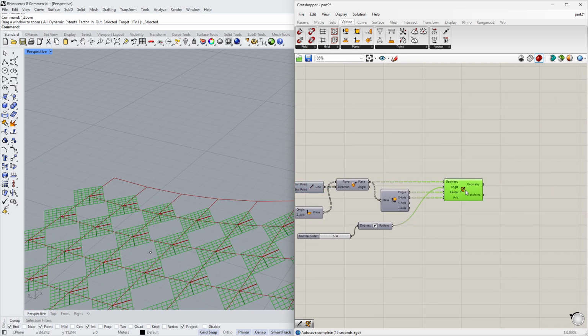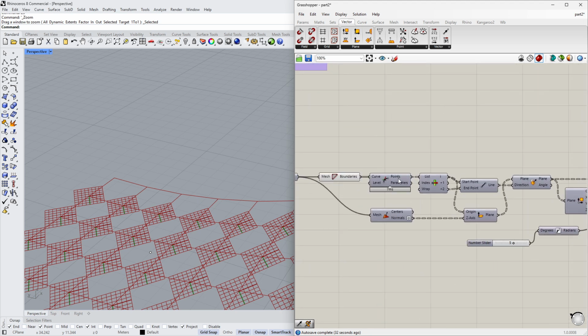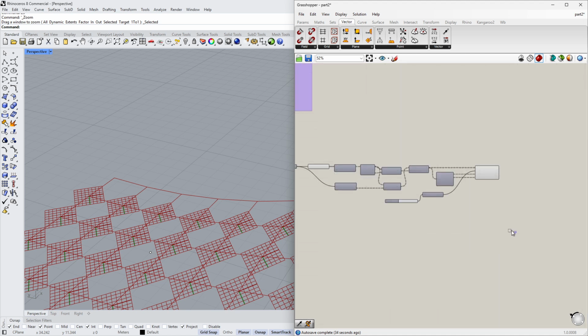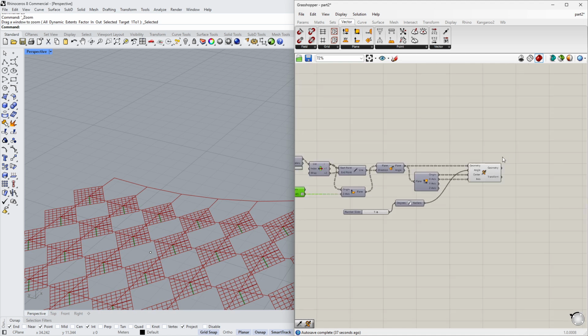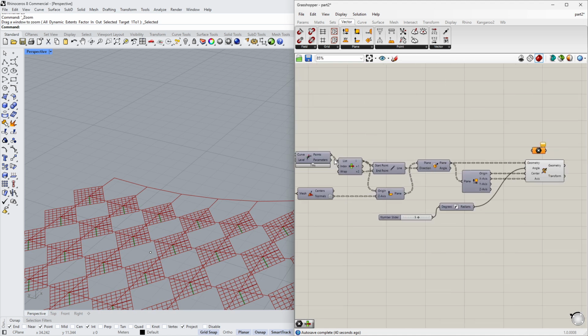So now we have our plane. The next thing we need to do is to project that double curved face on top of the plane so we get a straight flat panel. So for that, again, we need to get the points. Let me move this one a little bit down. We get again our corner points.